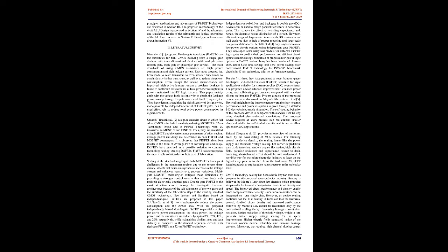Tripathy et al. [2] designed an adder circuit in which full adder CMOS circuits are designed using MOSFET in 32 nm technology length and in FinFET technology with 28 transistors in MOSFET and FinFET. Then, they are simulated using SPICE and the performance parameters of adders such as average power and delay are determined in both FinFET and MOSFET counterparts. It is observed that FinFET gives the best results in the form of average power consumption and delay.